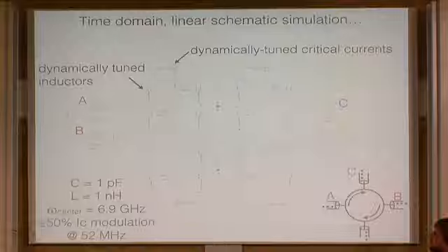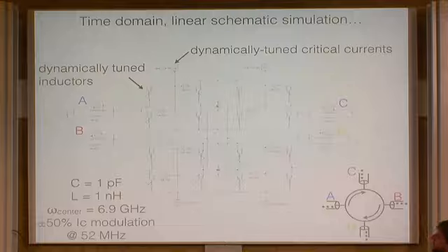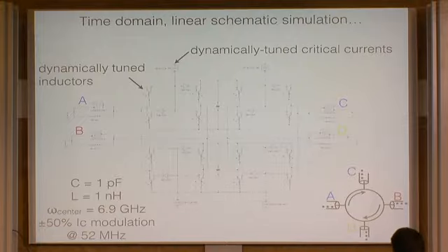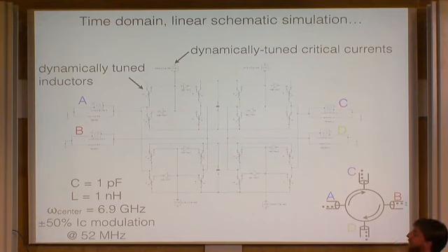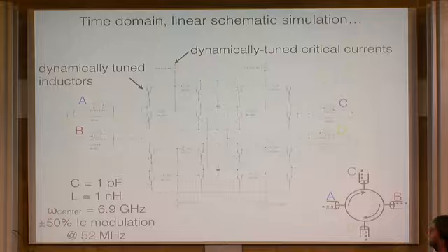So I can do a full time domain circuit simulation. I probably can't see this too well using Simulink and MATLAB, where I just draw my circuit, and now I'm thinking about modulating the inductances in each of the inductors, like that, and a bunch of sources. And I choose parameters which for us are quite reasonable to choose for actually building the circuit.